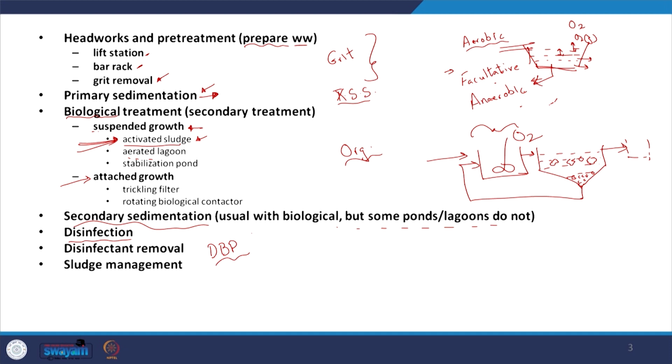And then sludge management, as in not all the sludge is going to be recycled. Mass balance, everything is about mass balance, we will look at that later. Depending on the mass balance, we will have to waste some sludge, and that sludge needs to be managed. Why is that? Microbes, sludge, considerable organic content: if you leave it out there, under anaerobic conditions, it's going to smell and decompose, with septic conditions and such.